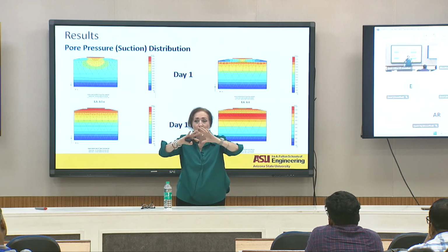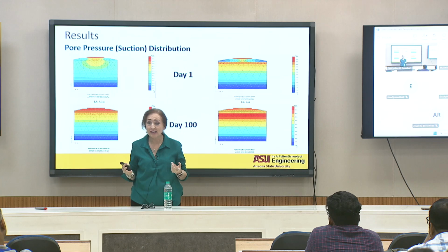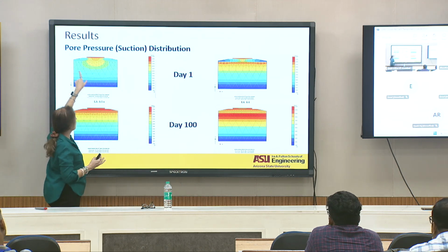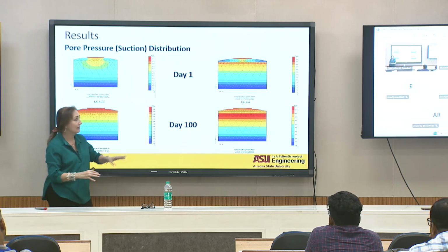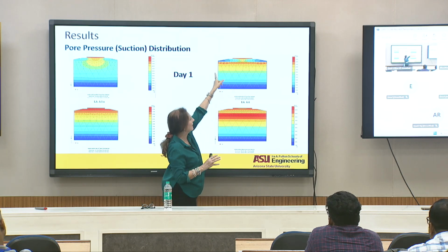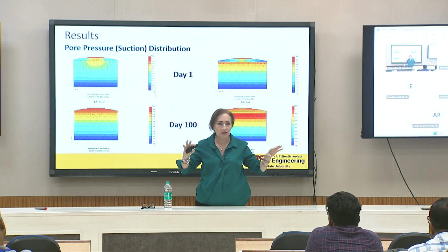So the water was basically hanging out on these drain materials or very high permeability materials, which is pretty bad, right? So the water did not infiltrate all the way down. So the resilient modulus in here might be lowering much more at the beginning than in here. In here, nothing happened to the subgrade. But the granular base material and the subbase material got totally inundated, okay?